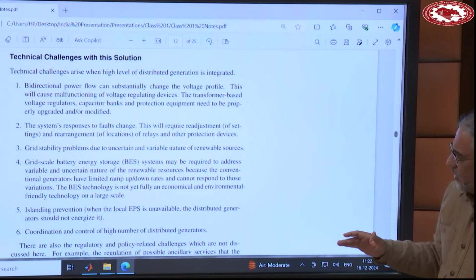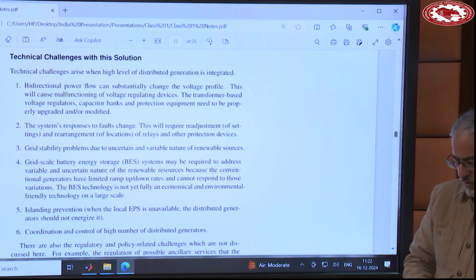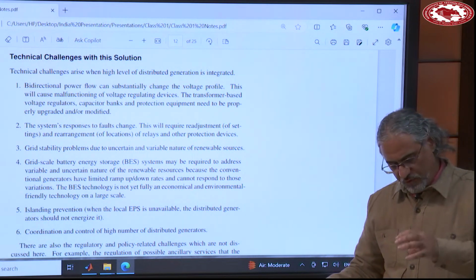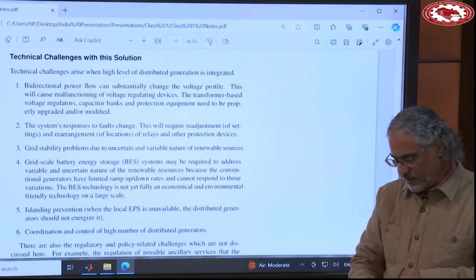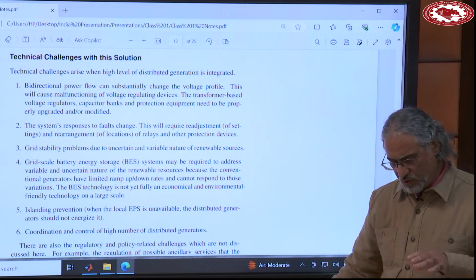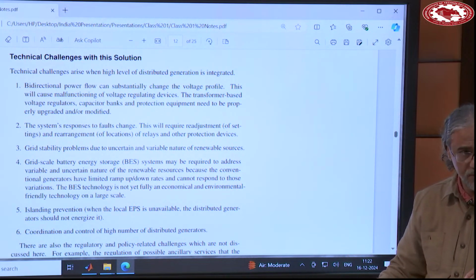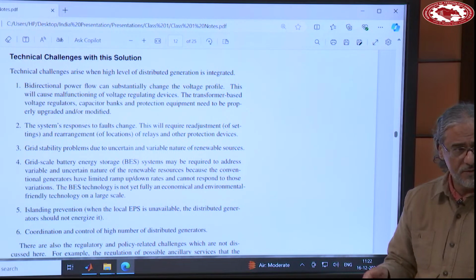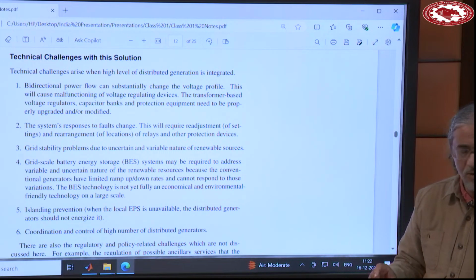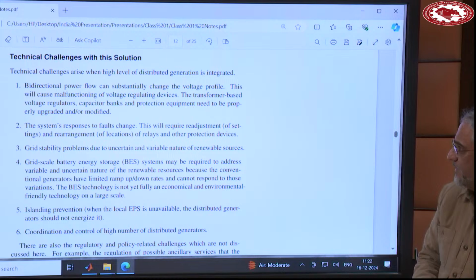So for a power system where power flows downstream from generation through transmission, this voltage profile is used first to locate this equipment, and second, to design the thresholds for those devices to operate, so protection relays.